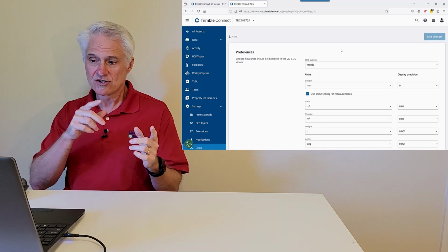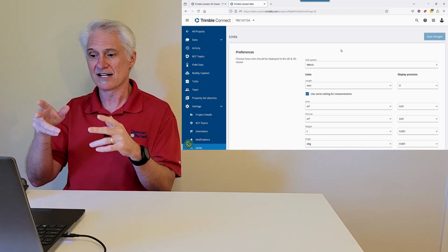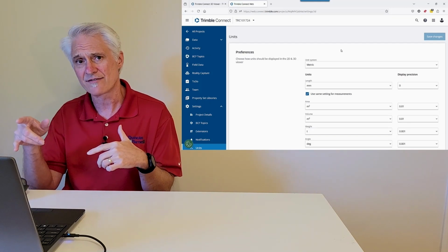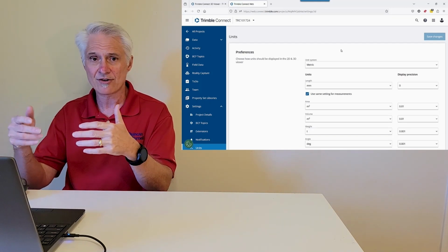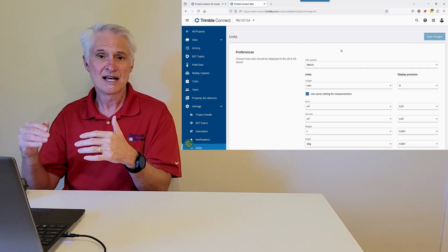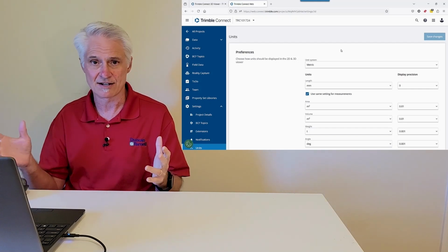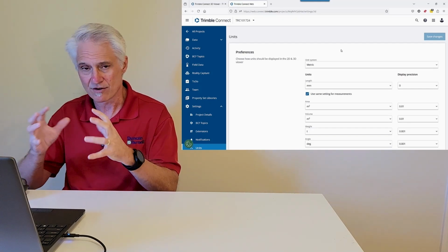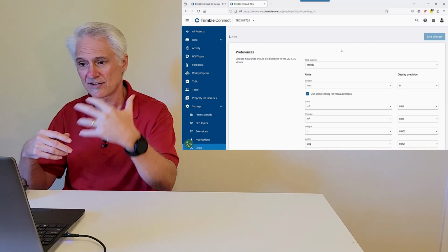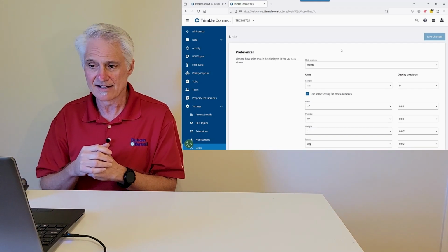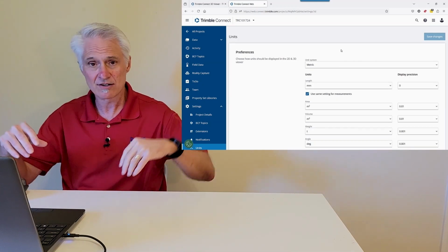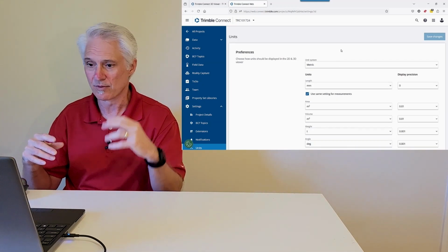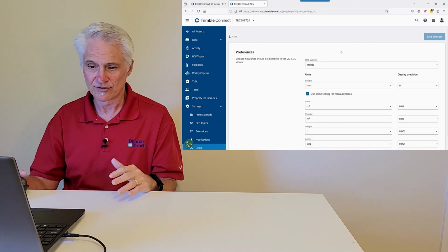Now, if I do structured E57, and I'll show you an example of this in a minute, if I do structured E57 in metric here when I set it up, once it's tiled, I can go change those units over to US survey feet and everything will be okay. It's just during that conversion process when you're uploading, it's tiling the data in there. It needs to be apples and apples with the units here and what you exported in the point cloud file, okay? So you set that up correctly.